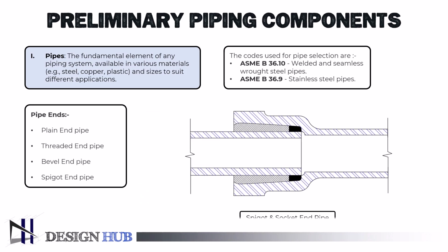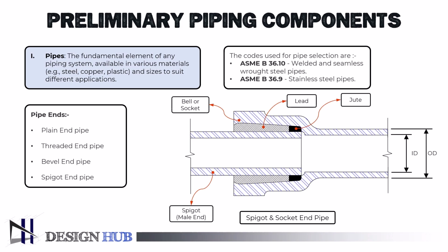The fitting end that is intended to be assembled into another fitting is referred to as the spigot. A fitting spigot end and pipe have the same outer diameter. Applications for socket end pipes and spigots include the following: sewer networks. In sewage applications, spigot and socket joints are employed to maintain waterproof systems. By enlarging the wall of one end of the pipe, a seal is produced between the male spigot and the female socket, forming the joint. When the pipes are connected, the rubber ring at the spigot end contracts and rolls away. Drinkable water: potable water is often transmitted and distributed via ductile iron pipes including socket joints and spigots.